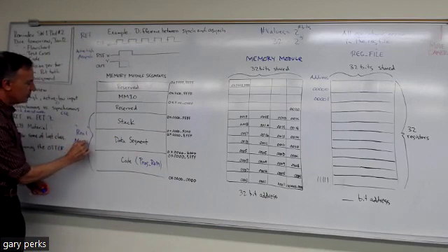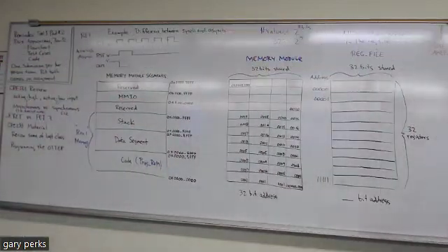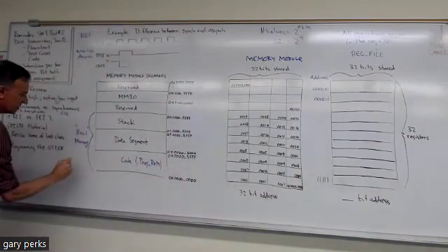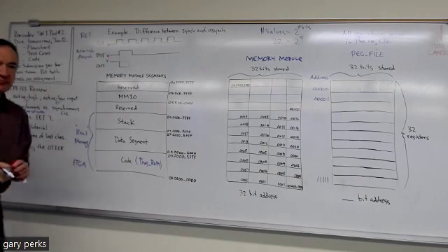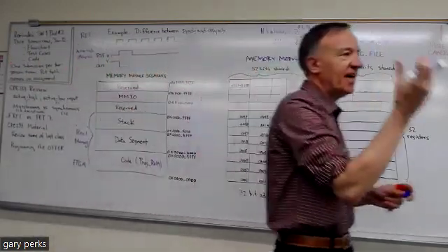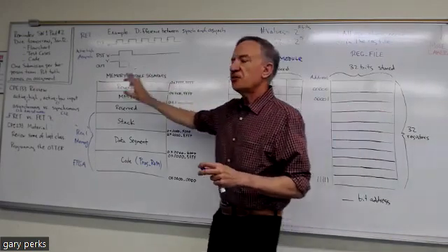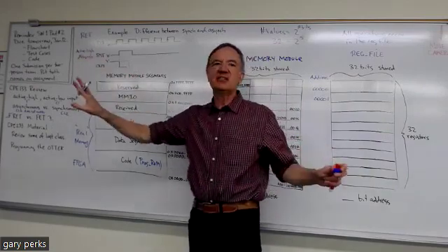And what's meant by real memory in this case is the portion of the memory module that's going to reside in the FPGA of your Basys 3 board. So real memory, these 3 segments, are actually going to be within the FPGA of your Basys 3. The reserved and the memory mapped IO, that's outside that FPGA.